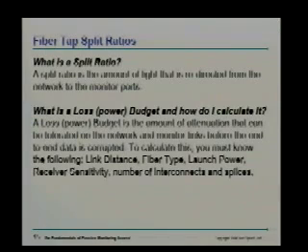All of those things factor into how much budget you have, or how much attenuation you already have, because by the insertion of a passive access tap, you are adding to the existing line loss on the network.